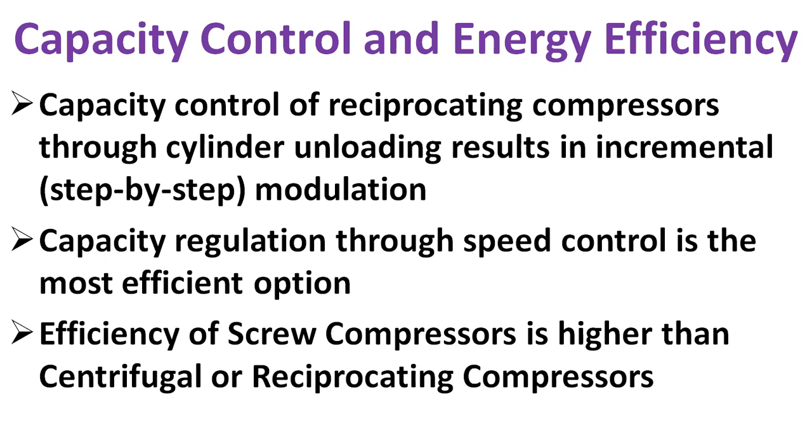Usually, when using reciprocating compressors in applications with widely varying loads, it is desirable to control the compressor by monitoring the return water temperature rather than the temperature of the water leaving the chiller. This prevents excessive on-off cycling or unnecessary loading and unloading of the compressor. Capacity regulation is also very important through speed control. However, when employing speed control for reciprocating compressors, it should be ensured that the lubrication system is not affected.